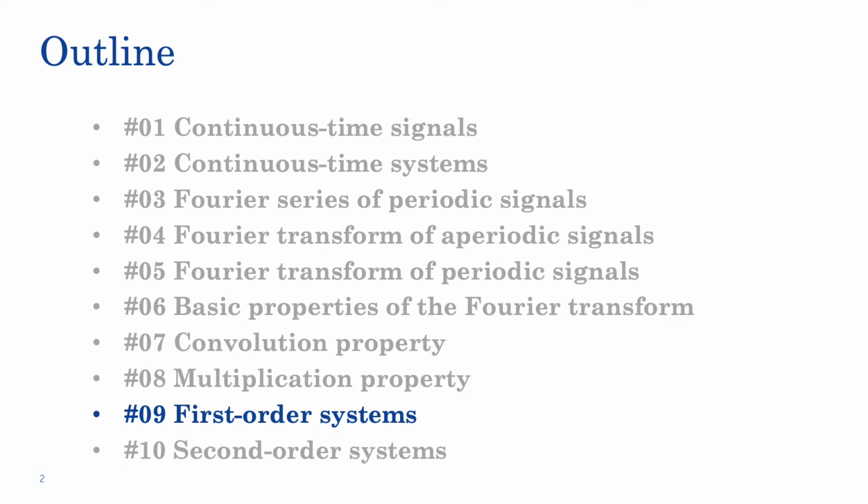In the last couple classes, we learned the important relationship between convolution and multiplication in time domain and frequency domain. This allows us to study the behavior of LTI systems through their frequency response H(jω). Today, we will first learn how to represent the frequency response of a system in terms of its magnitude and phase with the so-called Bode plots. Then we will focus on first order systems and we'll study the behavior of their impulse response, of their step response, and of their frequency response.